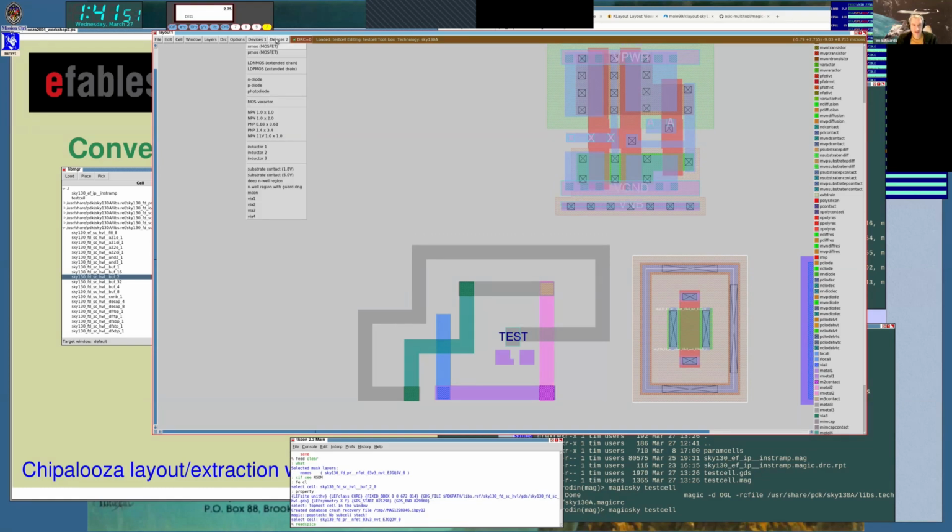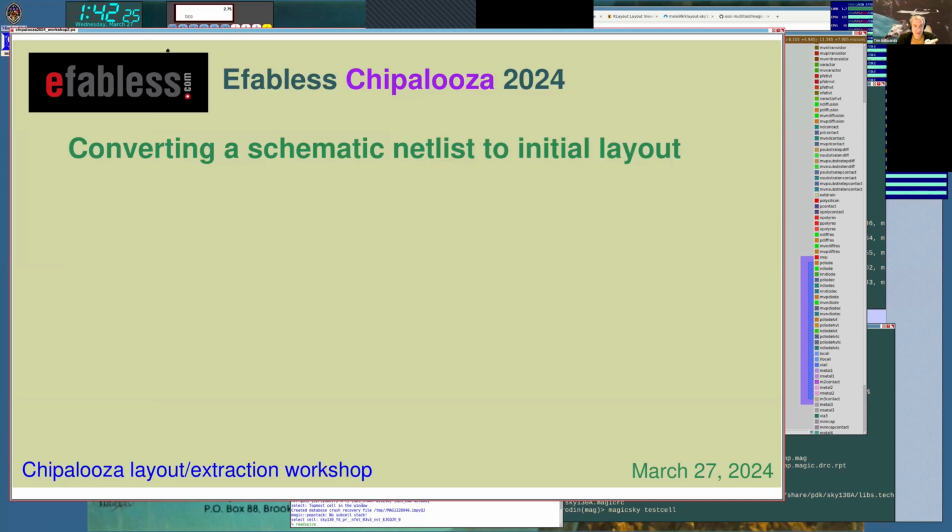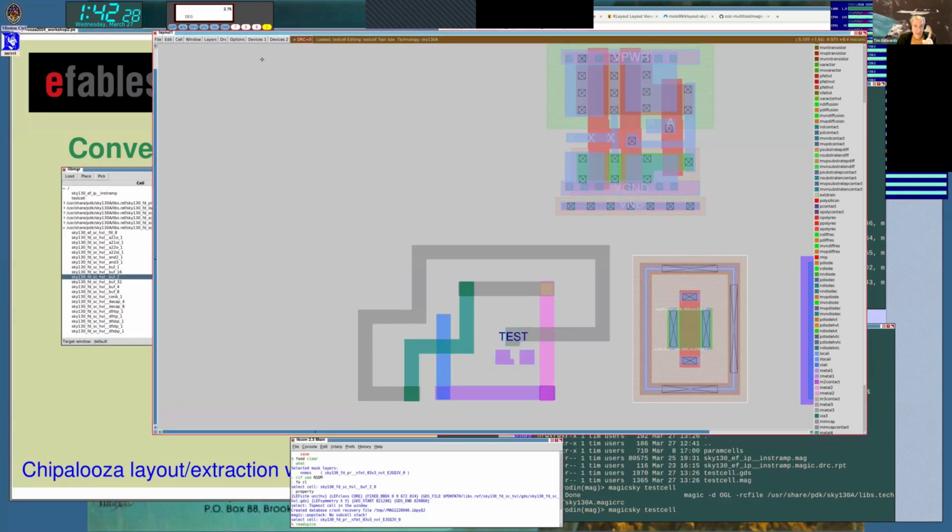But the PDK does have two menu items up here that are how you reach the generated cells. I put them into two different menu selections because otherwise the menu list gets really long. But you have MOSFETs, diodes, varactors, bipolars, you have resistors and memcaps and parallel plate capacitors. Is there a way to do generate from source from a schematic? That is just what I was about to demonstrate. So let me just do, since I was on that topic, let me go ahead and show that.